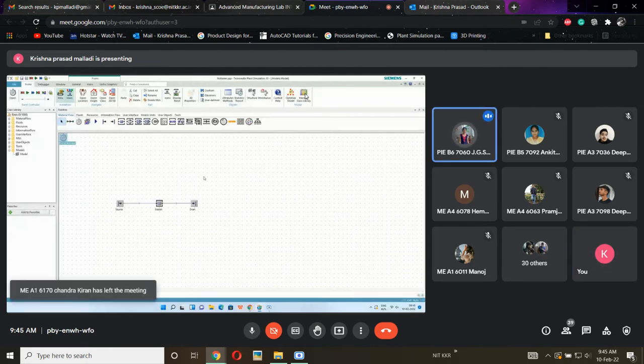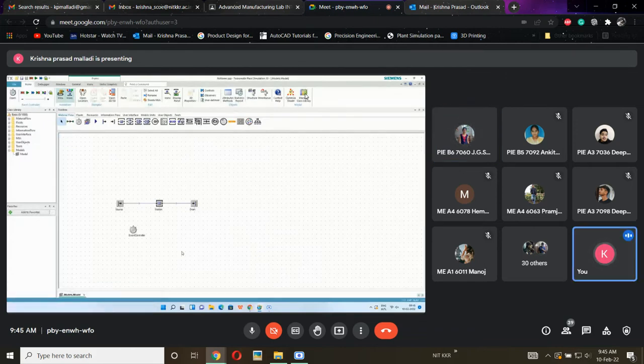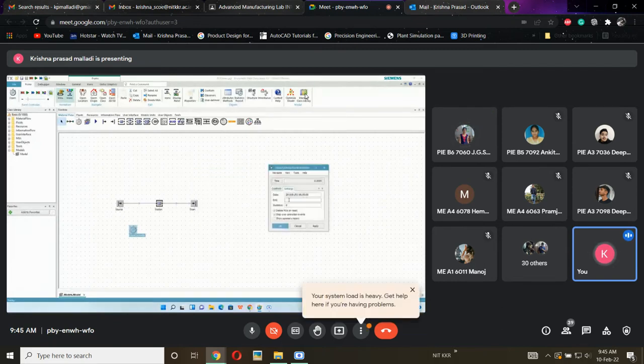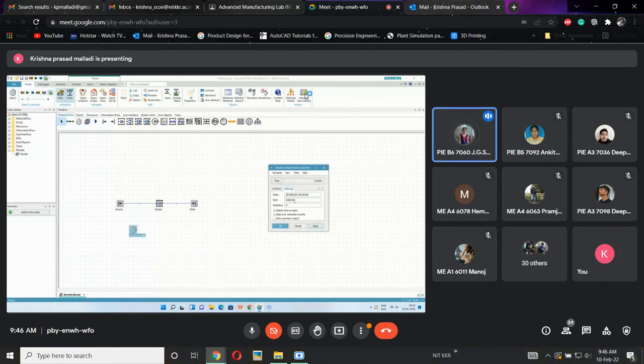So actually, we will set the time, sir, using the event controller, in the settings tab here. Let us say how many hours or how many days you want. Let us say 5 hours. Okay, apply 5 hours. Now I went to control.